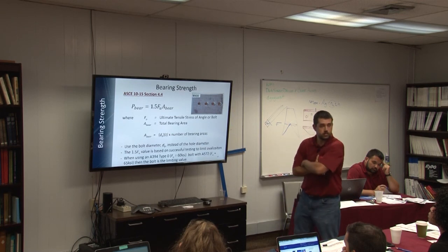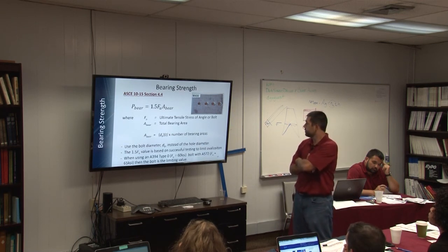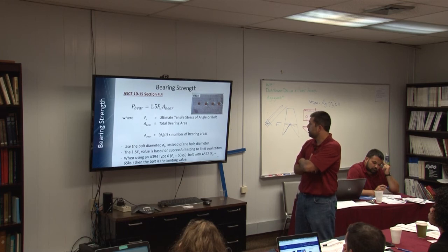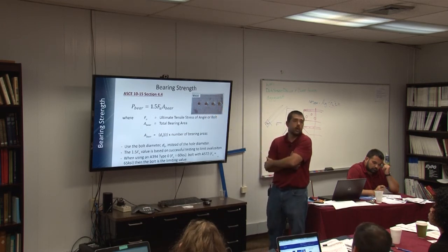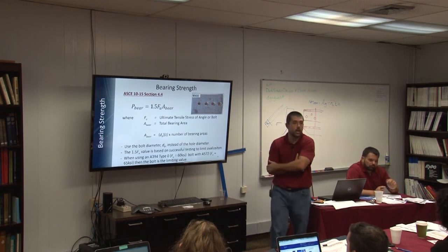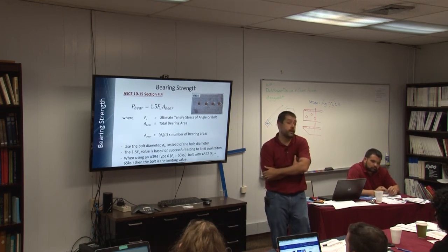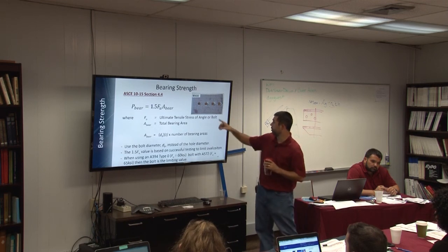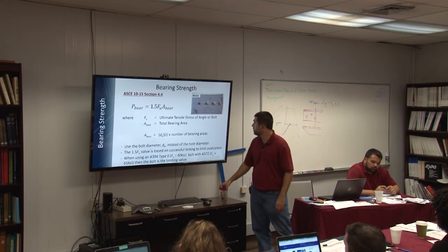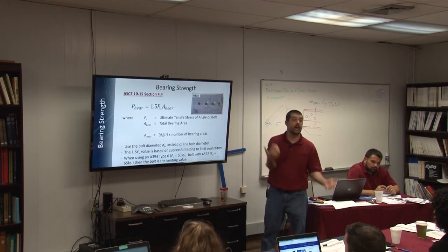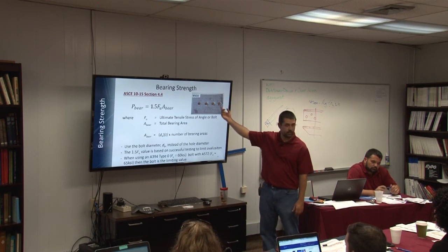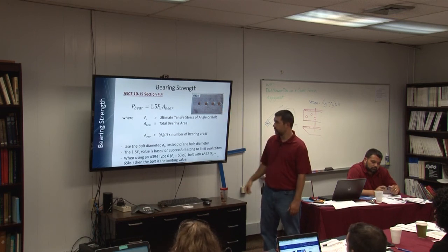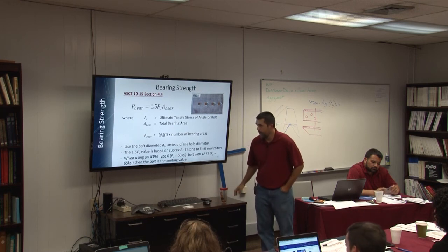I'm kind of confused as to what this really is compared to other things. This is basically saying it's going to start to elongate the holes. That's right. You're going to have something that looks like this, versus breaking the member. That's right. So it's not necessarily that the member's going to break. This might be a precursor to that, but you're basically ovalizing the hole. You're failing locally in this connection. Is it as catastrophic as some of the other things? No. But do you really want this to happen to your towers? No. Is it common that this happens versus the member breaking?